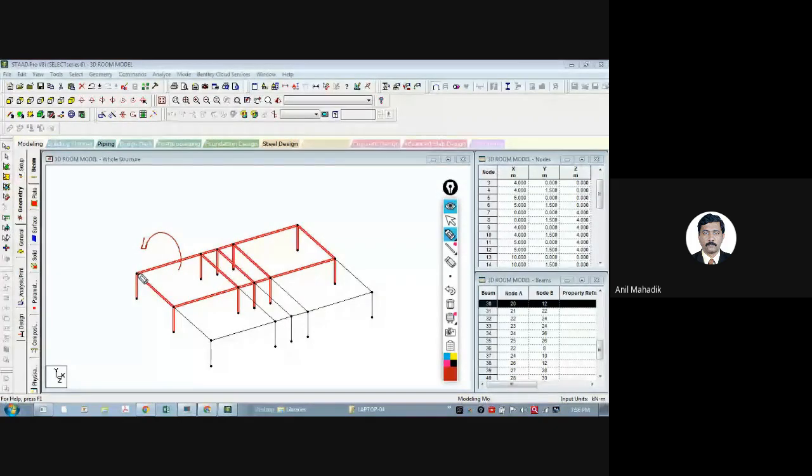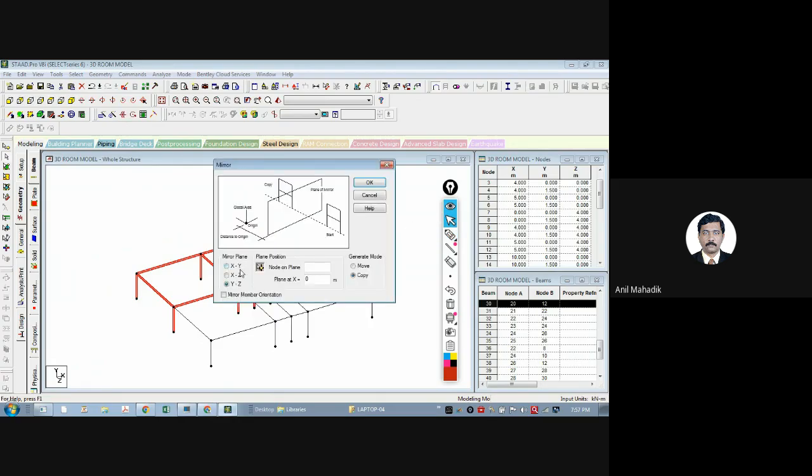So what will be my plane? Plane तो ये रहेगा ना, which is xy. And यहाँ z पे z रहेगा मेरा, which is let's say अभी 4 मीटर ही लेता हूँ, लेकिन अभी ये z देखो, ये z डायरेक्शन ऐसे था, which is positive, and this is negative. So I will put -4 meters in the command. So go to the mirror, xy plane, and z is equal to -4.